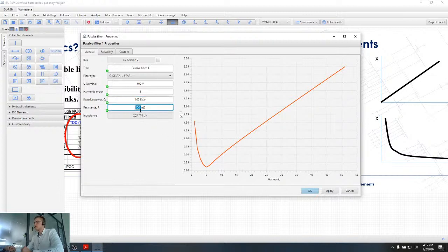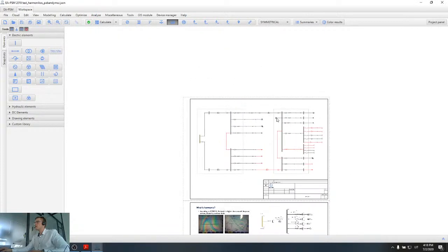So the smaller the resistance, the better the filter, and the more harmonics will be mitigated, consumed. And if we go to frequencies higher than the fifth, let's say a frequency equal to 500 Hertz, you can see that this filter has inductive impedance. For this harmonic, it means that if we have a 500 Hertz harmonic, this filter will work as a simple inductor, a simple linear load for this particular harmonic. So our filter will try to mitigate harmonics by consuming them in the electrical network.